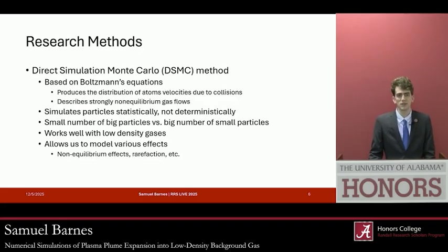Technically speaking, you could have used what's called the molecular dynamics method, which essentially simulates every single particle, and it simulates that deterministically and is fully focused on modeling every particle and where it moves and how it collides. But the computational overhead to use that instead of DSMC is much greater, and the results that we get using DSMC are just as good as we would get using that, and takes far less time to run.